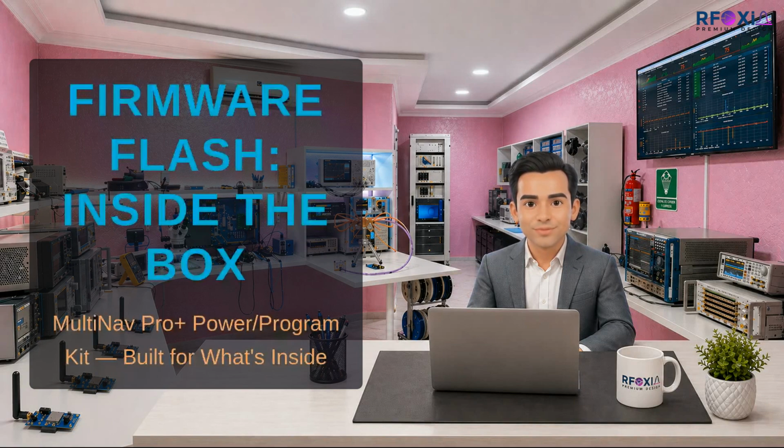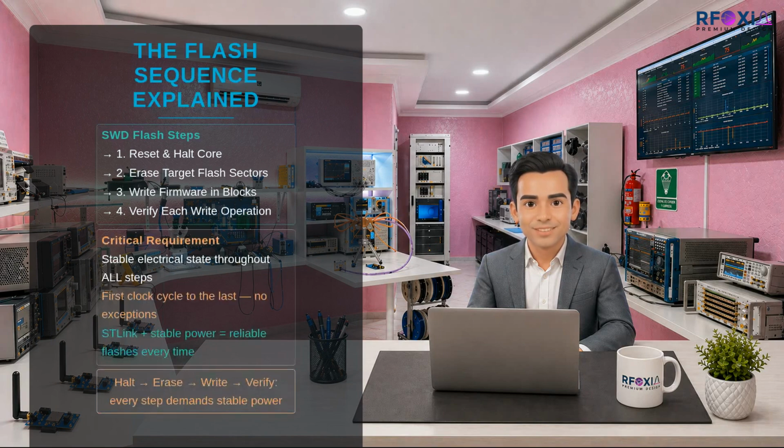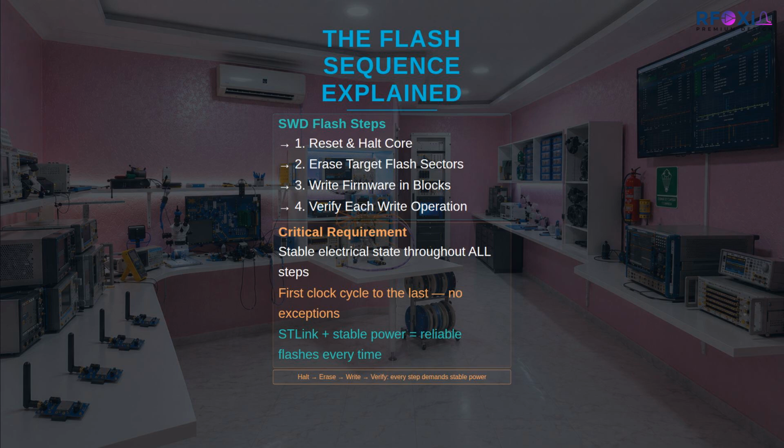When your ST-Link programmer initiates a flash sequence, it establishes a debug interface with your target microcontroller, typically over SWD, serial wire debug. The programmer sends a reset, halts the core, erases the target flash sectors, and then begins writing firmware in blocks. Each write operation is verified. If the verification fails, the programmer either retries or aborts depending on its configuration. That entire sequence, halt, erase, write, verify, depends on the target device being in a known stable electrical state from the first clock cycle to the last.